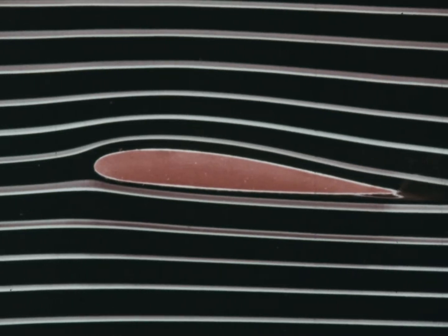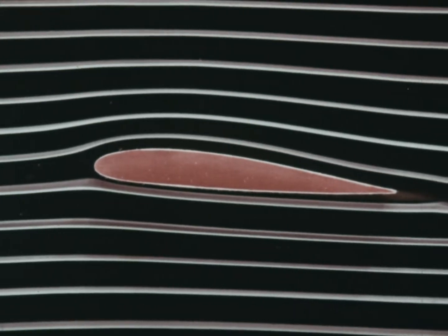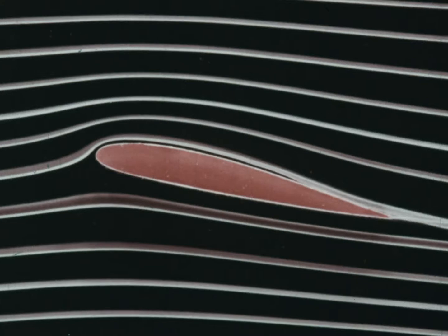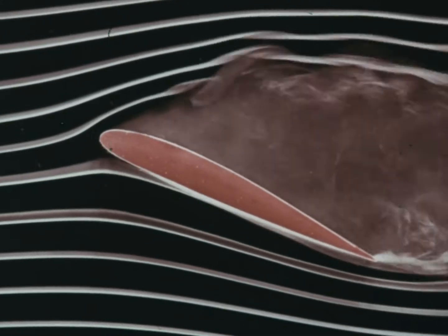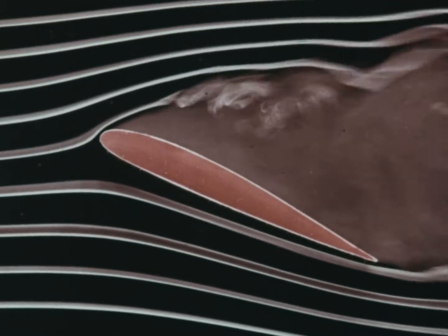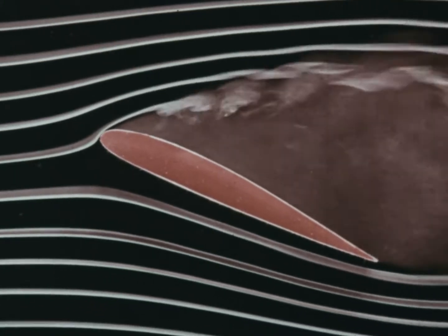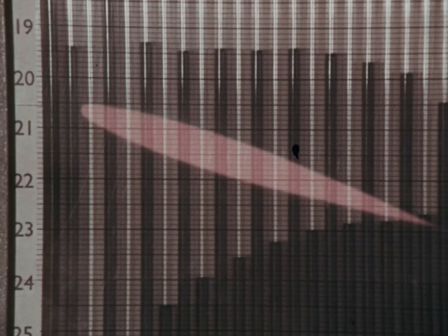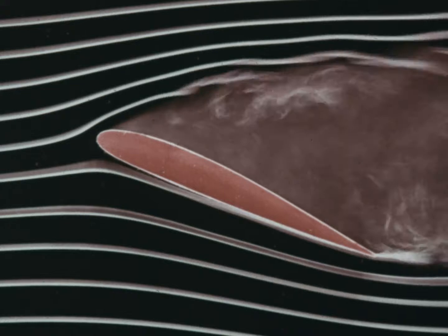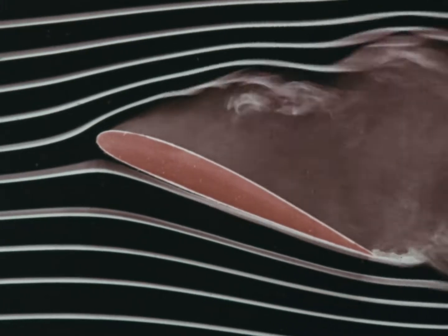But the extent to which we can increase the angle of attack to the relative airflow is strictly limited. If we increase the angle by more than a certain amount, depending on the type of airplane, this happens. The airflow breaks up over the upper surface of the wing. The pressure pattern becomes unstable. Lift decreases sharply. The wing has stalled. This can happen at any speed once the wing has reached the critical angle.